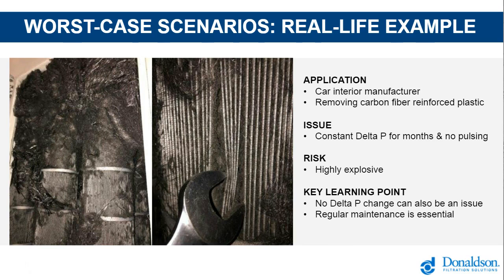Our customer called us because the units were running 24/7, but the delta P was always at the same level. No pulsing happening to clean the cartridges. We were talking about reinforced ATEX units with high explosion danger because a special resin was used. We're talking here about CFK fibers, the kind of fibers which are used in automotive manufacturing for car interiors. And when they really accumulate, they can be really dangerous. They can really lead to explosions.